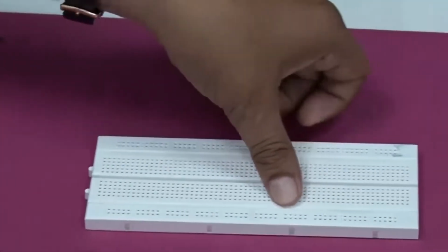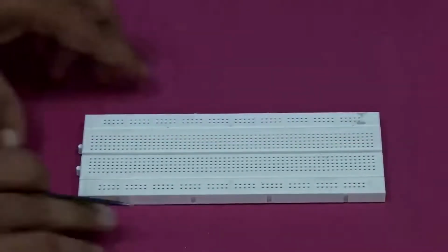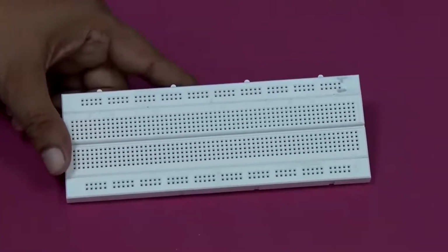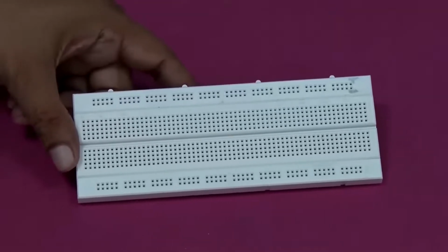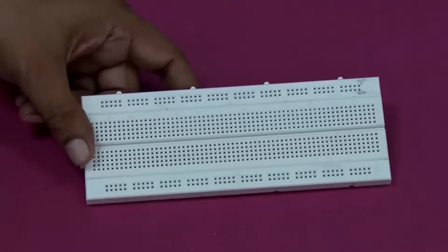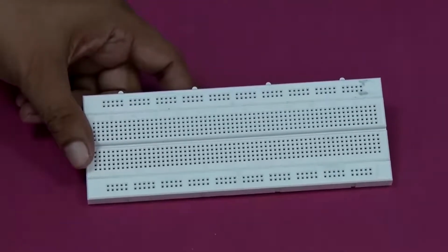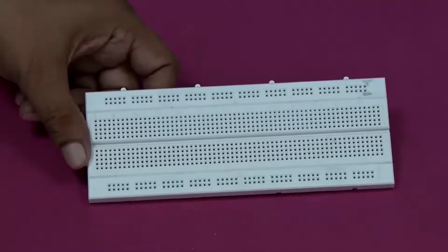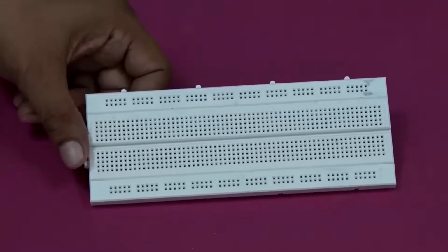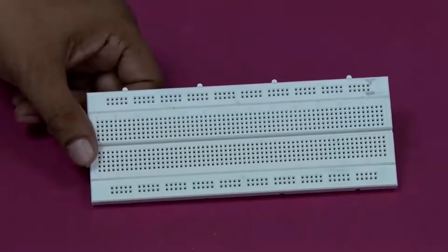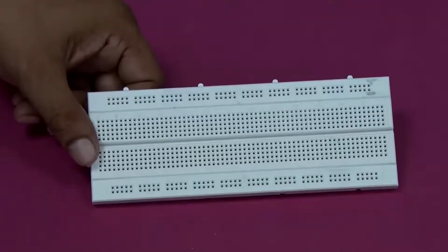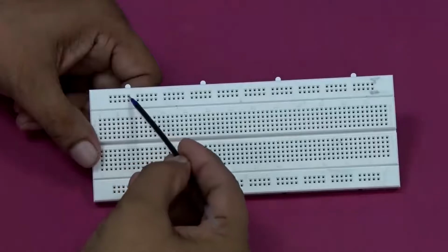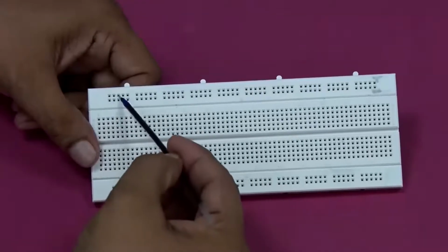So, now Ranjit has to help me. As I said, all the negatives of the battery, the black terminals of the multimeters, the emitter, are all connected to the zero potential line. They have to be connected to each other, which we will be calling zero potential. On this breadboard, I will be using this line here for that zero potential.